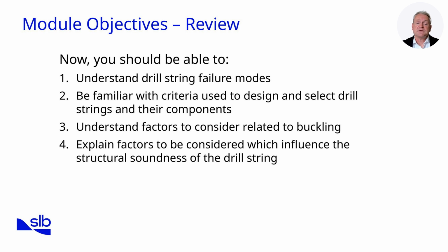From there, we shifted to the bottom hole assembly, discussing how different configurations are suited to low, medium, and high angles. We explored how the available weight on bit changes with inclination and why this matters for efficient drilling. Finally, we introduced the curvature index and stability index, two practical tools that provide comparative guidance in assessing drill string performance across different well designs.